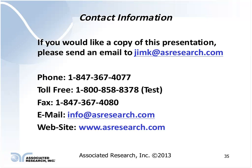Wearing high voltage gloves is another way to protect the user. Having the user stand on a high voltage insulation mat to ensure that they are not at a ground potential is yet another way to protect the user. There are a whole slew of things out there that you can do to protect your user. I've just named a few. If you want more information on protecting your user while running a Hipot test, I would recommend you visit our website, asresearch.com. You're going to find a tab for support, and there's something called the Operator's Guide. And the Operator's Guide talks about things you can do to protect your user.